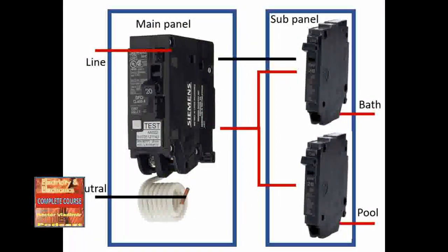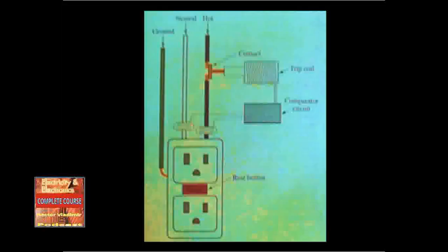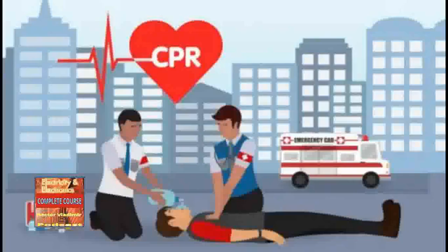Ground fault protection devices are not limited to power outlet designs. They are commonly incorporated in GFI-style circuit breakers. Non-GFI power outlets can be used with single GFI type breakers. The non-GFI power outlet will then provide the same protection as a GFI outlet. This is a very cost-effective solution when several outlets are required to be GFI.